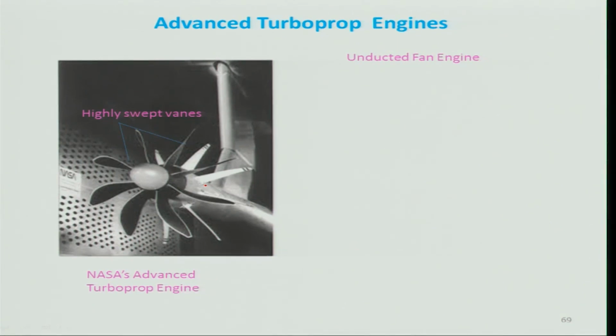You will overcome the problem of the asymmetric thrust, and it will be more efficient, because the air is moving through the blade with a swirl component, which does not give thrust. What gives you the thrust is the axial component, so in this case you will avoid that loss.